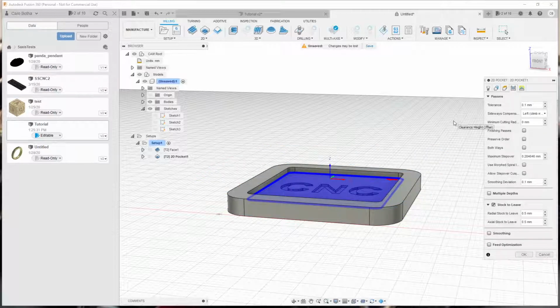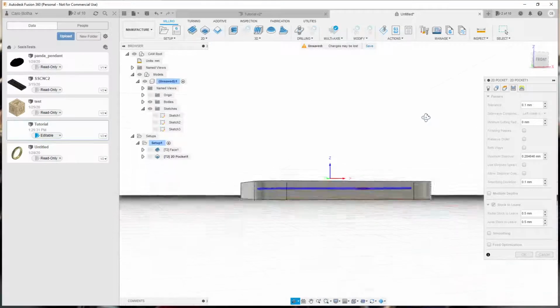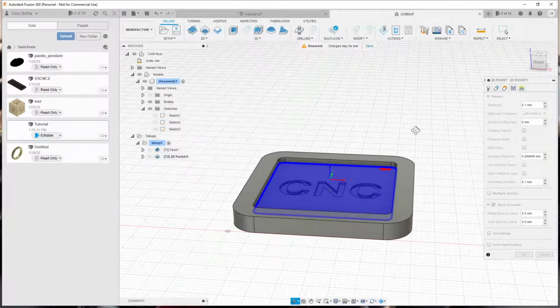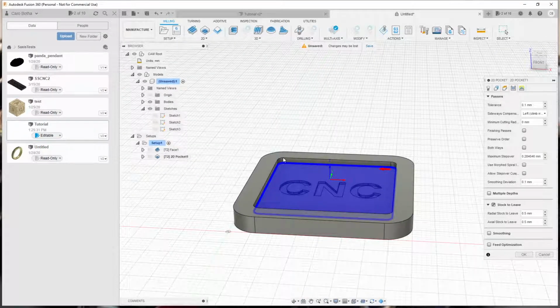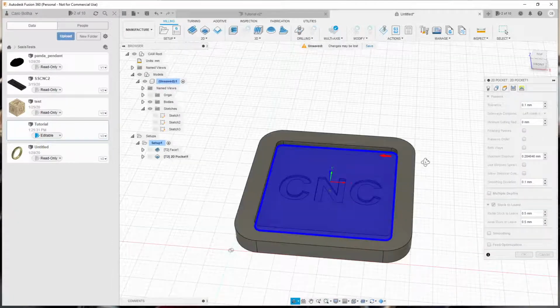Then let's look at our passes. We're using a fairly big 3.17mm, but that is 1.5 deep, so hypothetically that's what it can cut in one pass. You may want it to have multiple depths. If you're cutting something very sticky like platinum or so, you may want to do this in multiple steps irrespective, but let's start again from the top. Okay, so that tolerance thing we spoke about before, you can kind of see if you get in here.